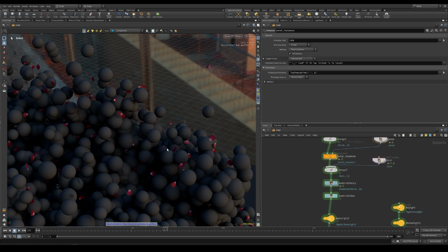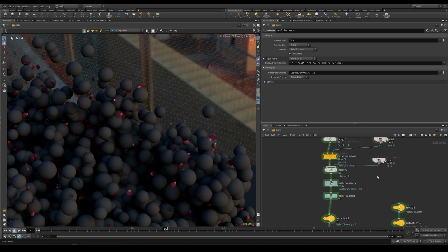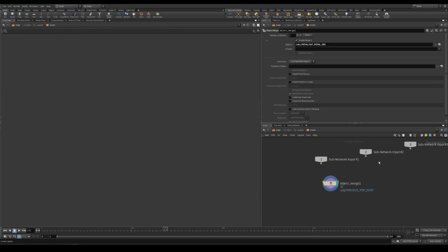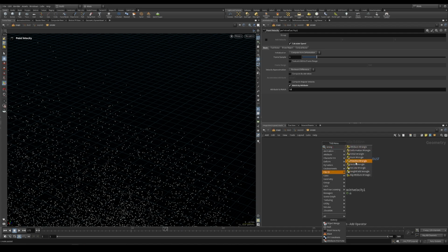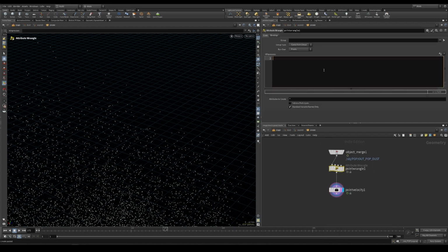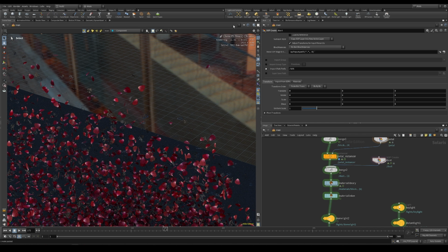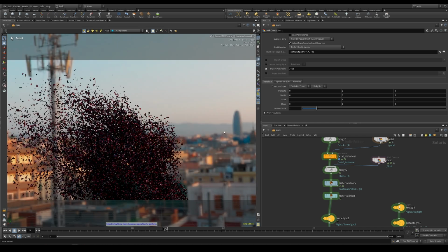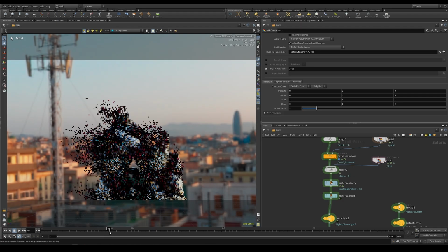And of course we didn't change the p-scale, so let's go back into the petal instancer, let's take the point velocity, because we also need that. And inside here, for the dust, let's paste the velocity, and let's take a point wrangle, we just hard code some p-scale value, so f@pscale is equal to, let's say, 0.01. So if we go outside, we should fix, yeah, the p-scale. Let's see from the camera what we have. And I'm quite happy.